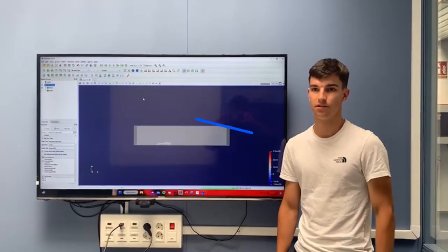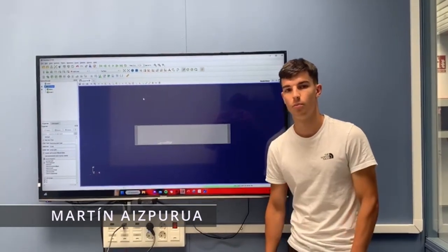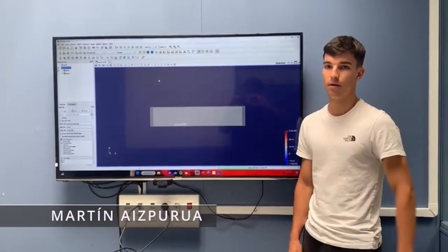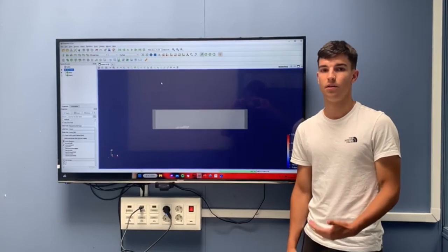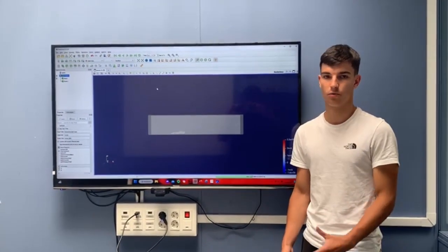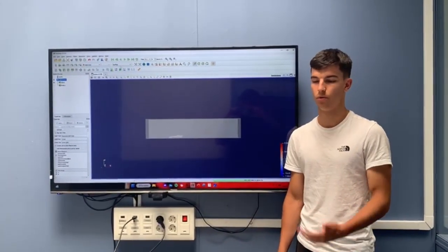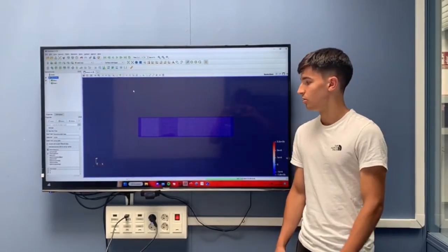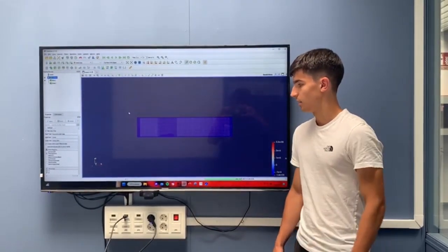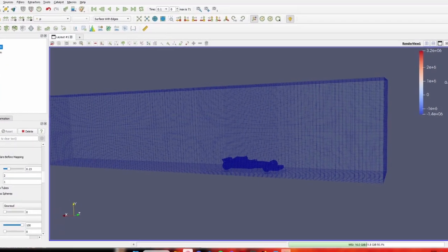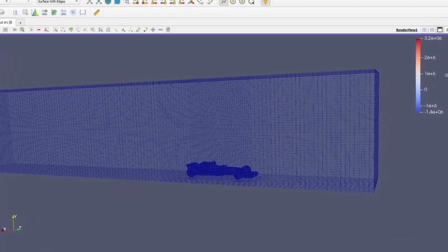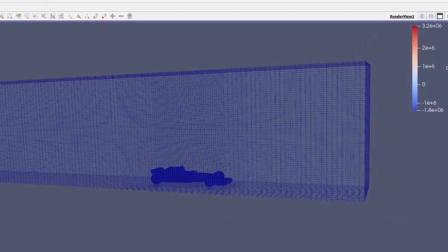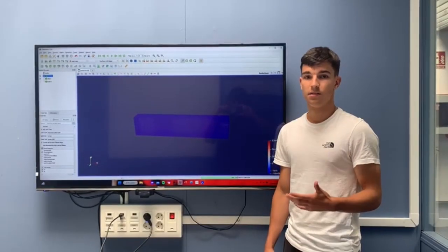We've also done a CFD simulation, and for it we've used OpenFOAM, and we are running it in parallel. First to say that we didn't have the resources and our computer wasn't so powerful so that we could get mesh independence or volume independence. So for this reason, we just calculated a simplified mesh that wouldn't take so much time and didn't have so many blocks.